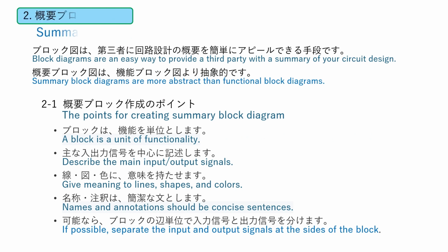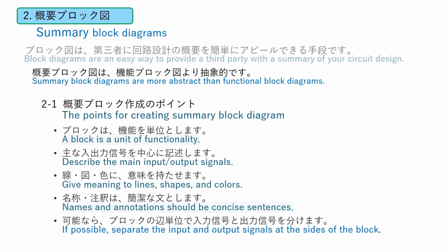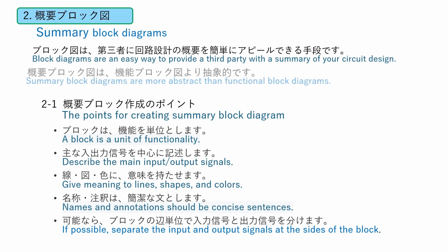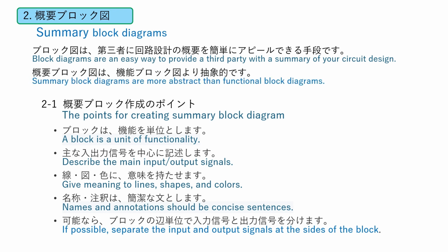2. Summary block diagrams. Block diagrams are an easy way to provide a third party with a summary of your circuit design. Summary block diagrams are more abstract than functional block diagrams. Don't you get depressed when you see circuit specifications that the opening sentence describes at length? I think it will be solved a little if you add a summary block diagram at the beginning. Here are some items that I keep in mind when creating block diagrams.